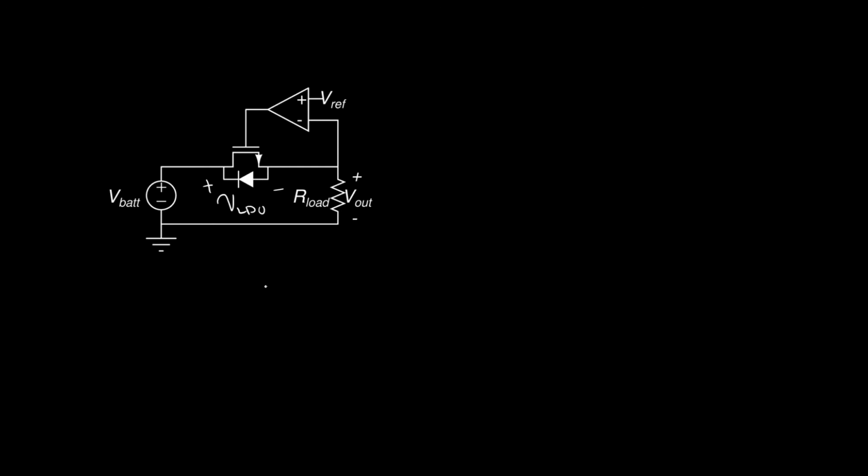Very simply, we can use KVL. We can think about this single loop, right? And we can notice that if we go around this loop, voltages which align with my direction of the loop are on the left side of the equation. Voltages which are anti-parallel to that direction are on the right side of the equation. And by KVL, the things on the left side should be equal to the things on the right side.